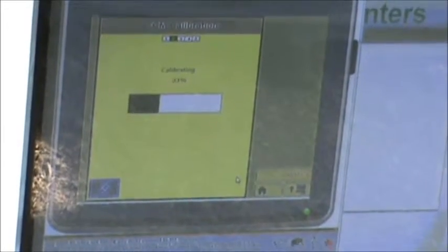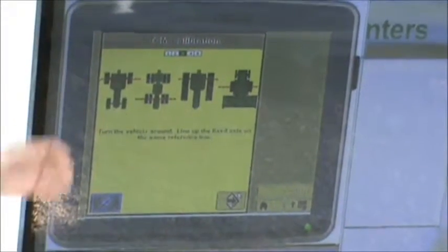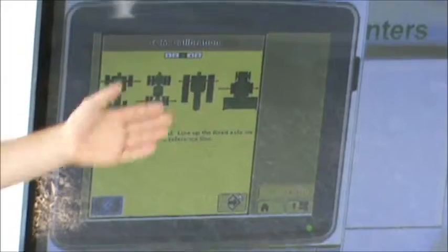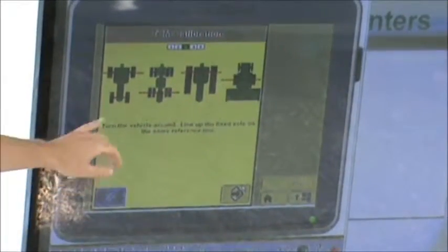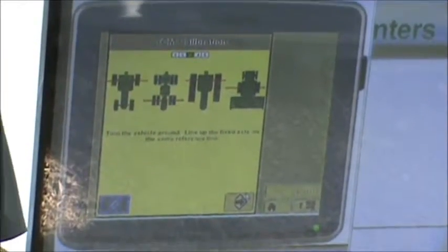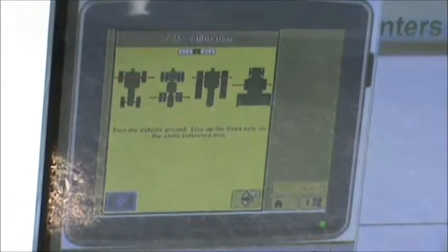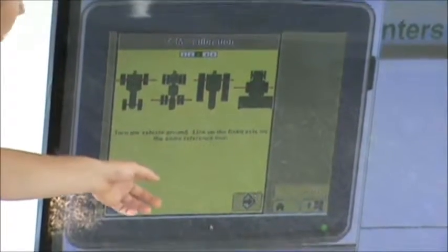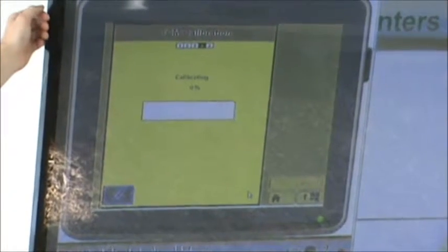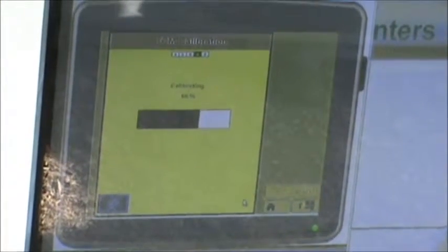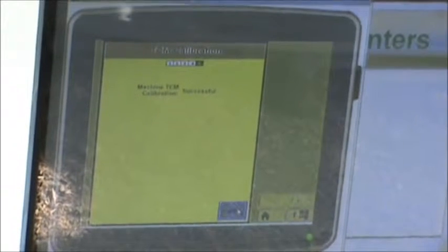and it's going to calibrate the TCM for the direction you're facing. So say we calibrated it facing east. Once that calibration is done, we actually have to turn the vehicle physically around. So instead of facing east, you're facing west with the non-steering axle lined up on the same point. You hit the button again. Your TCM is now calibrated, and your lines and points will be more accurate, so we can make better decisions later in the year.